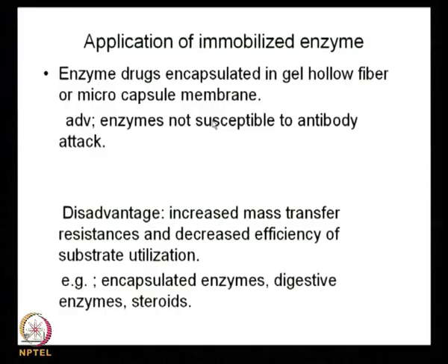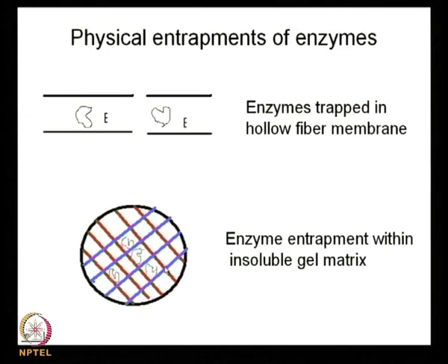Yeah, but basically what will happen is there will be, absorption is a part of what? Mass transfer. So, essentially, see, the difference between this and the earlier thing is that earlier we had a simple reaction taking place because it was dissolved and the substrate was in excess. But now, let us go back to one of the pictures, see for example here the bottom picture. So, the enzyme is deep inside the matrix. For the substrate to reach this, there is a lot of mass transfer resistance that it has to overcome.